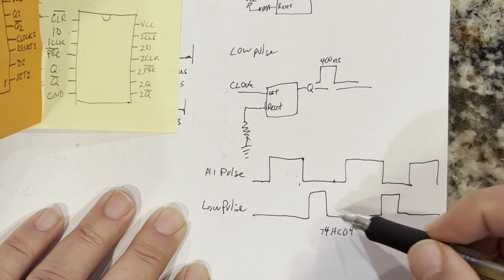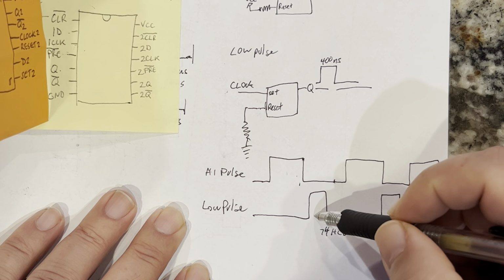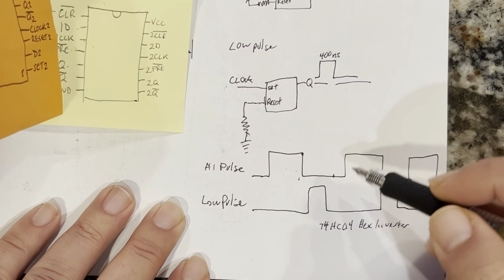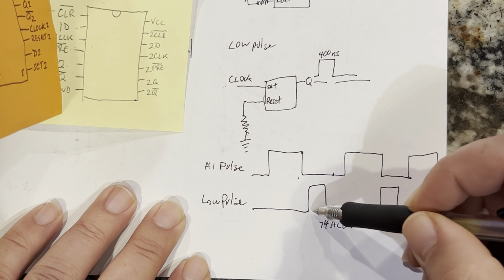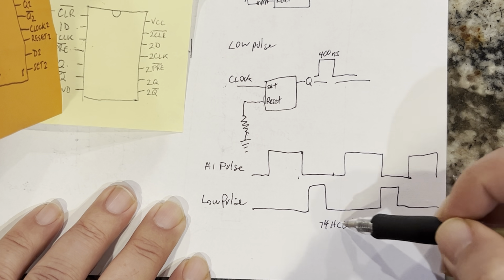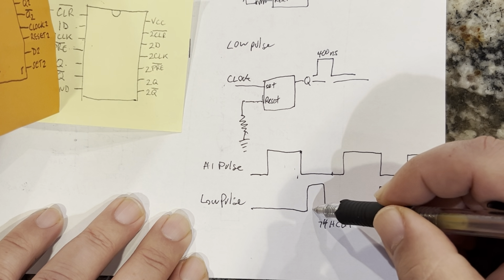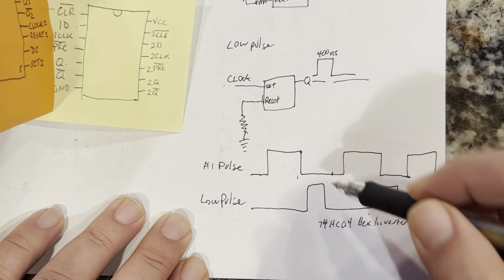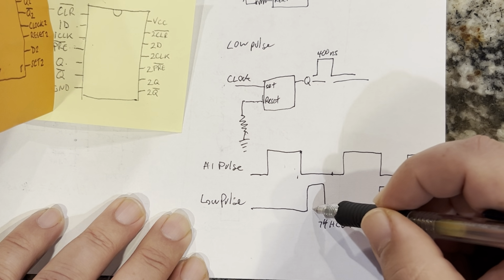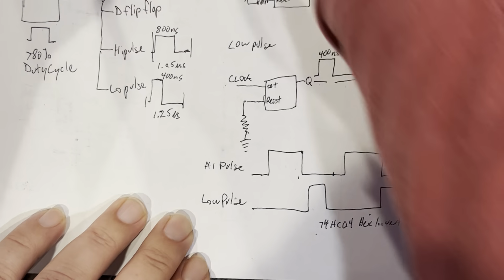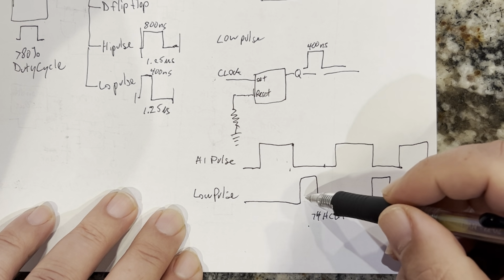That was great, because every time you invert this signal, there's a propagation delay in this hex inverter. But that propagation delay is about 15 nanoseconds. This is a quick chip. And so every time I inverted the signal, and you have to invert it twice, I would get it to go a little bit more forward, and then a little bit more.